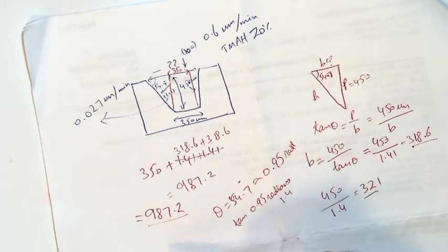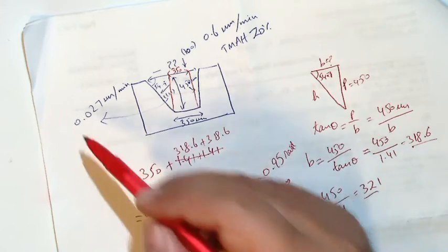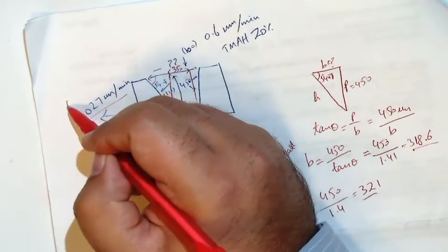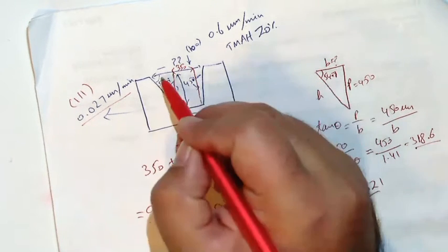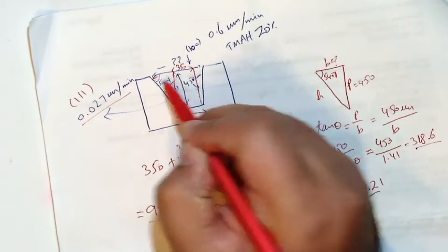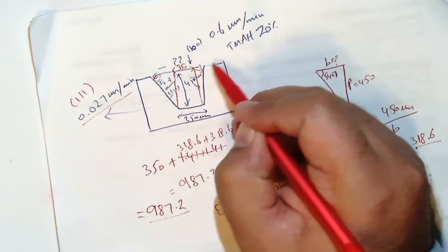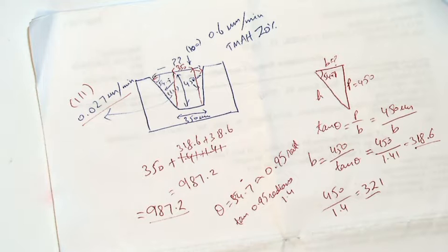But I also gave you that it is etching in the 111 direction on the sides also. And we have not accounted for that, or do we have to account for that in designing our mask? Because if it's on the sides, it means maybe it's also etching on this side, right? And also on this side. So from where we started, at the end, maybe after 1 hour, 2 hours, it's a long process normally.